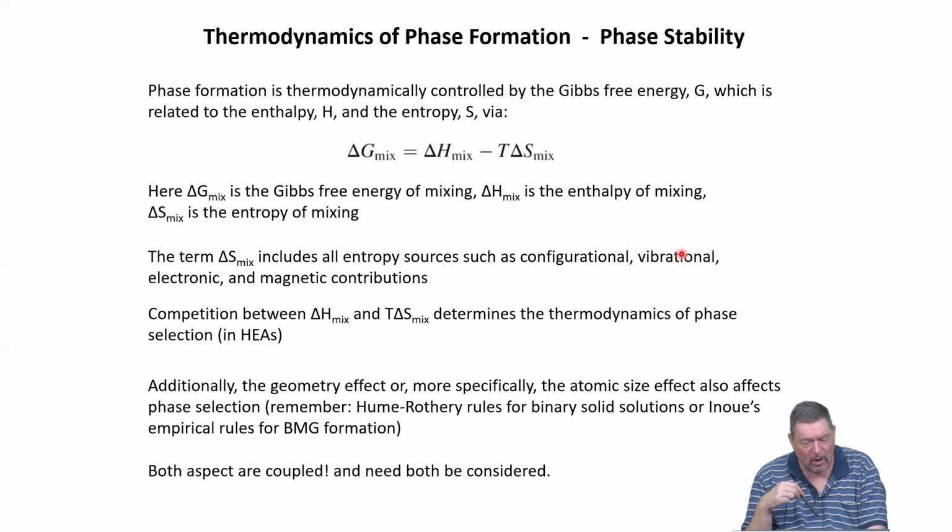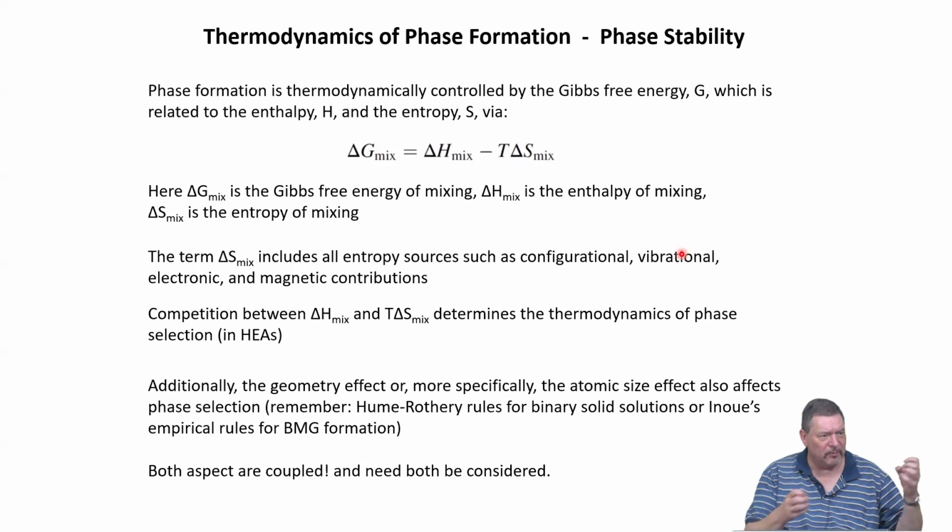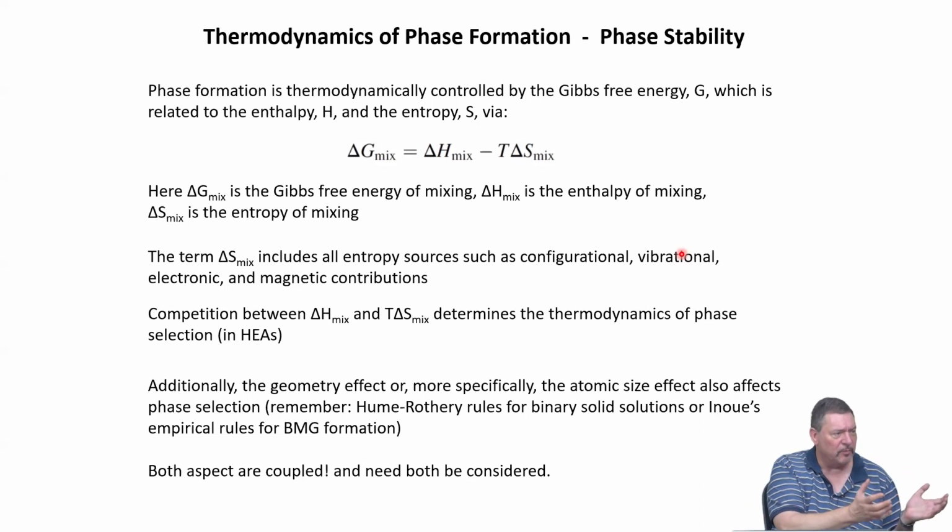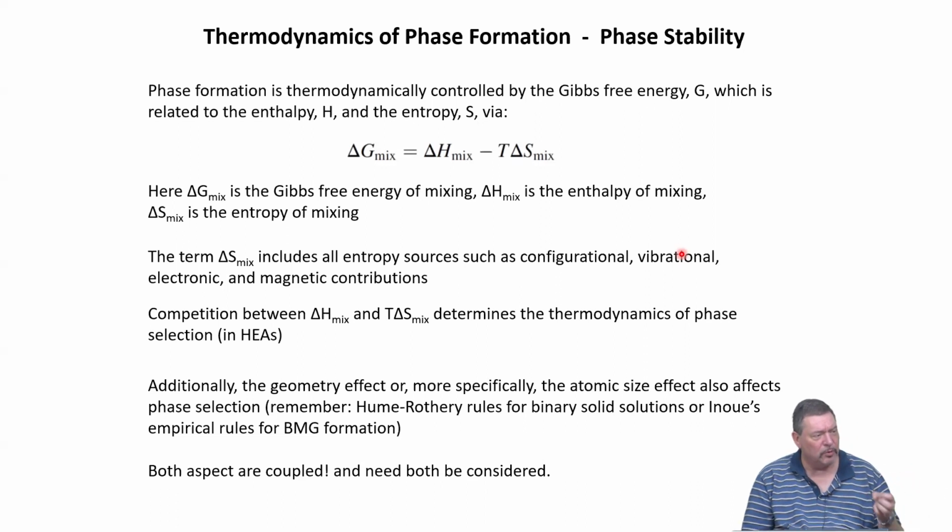And obviously we also have geometric effects, like the size of an atom. The size of an atom is something which is highly undefined by nature, because it will change whether you put this atom together with equal atoms and form a crystal lattice, or whether you put this atom as an impurity into a different lattice, because the electronic interactions will be different, and that means the effective radius will change.